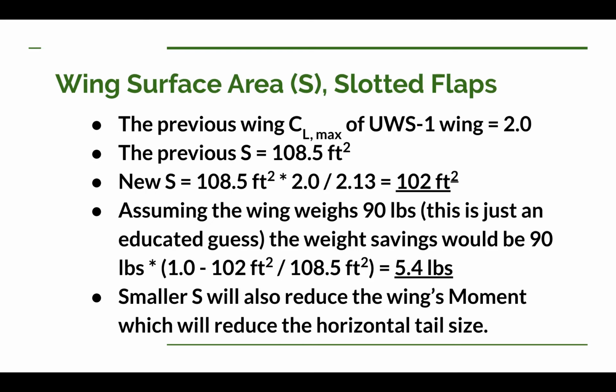Well, that long hinge is going to have extra hardware to connect it to the wing and to the flap, and that would add weight. So I'm guessing that probably in the long run it would just even out. The extra hinge material would probably end up being around 5-6 pounds, so the weight savings will probably even out.